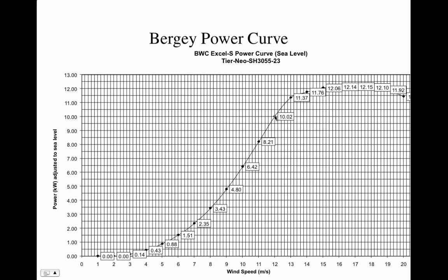10 kilowatts. Is that right? Yeah, 10 kilowatts. And so you can see that if we double the wind speed, we get a lot more power out of this machine. It should be 8 times, and that's not working out to 8 times. Let's try something else.